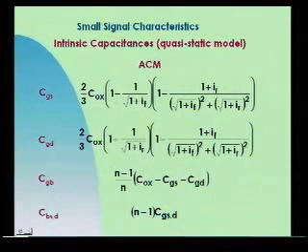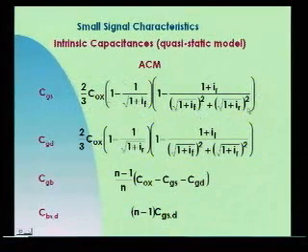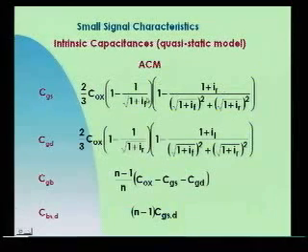If you are working in saturation, which is the case of most circuits, where we must have the transistors operating in saturation, the equations will be still simpler, because the dependence will be upon only one component, only on IF, which is also called the inversion level. It gives a measure of the inversion level of the transistor. I will talk about this in the next class.